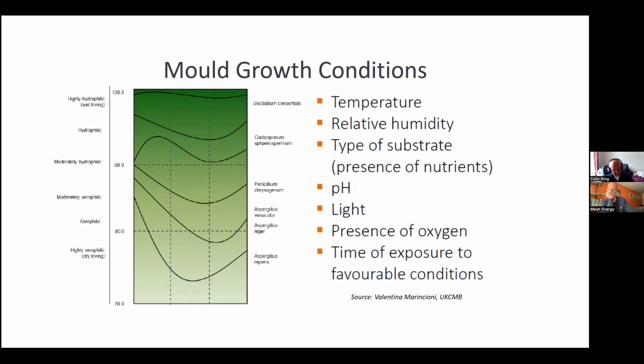Yeah, well, with that, what you actually need is a coherent strategy of how you want that building to perform. So if you look at more modern buildings, they are of cementitious material that resist the passage of moisture because they're strong, because they are consistent. So basically, they work by keeping the water out. So if you have a more modern building and your building is vapor closed, then the insulation needs to be vapor closed. So you have a coherent strategy of moisture movement across the structure.